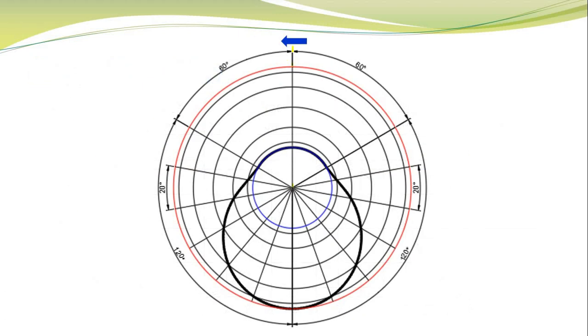So the first thing was you had a dwell at the beginning of 60 degrees, so done. Then from this point onwards you had 120 degrees rotation of the cam in which the follower was moving outside. So you can see from this point to here I have 120 degrees, and then for the next 120 degrees rotation of the cam, the follower is going back to its original position.